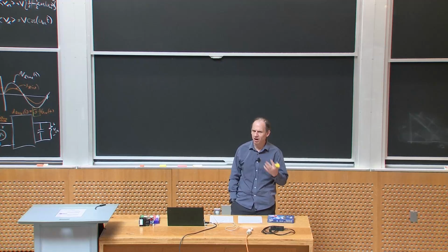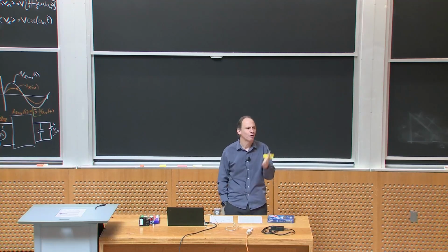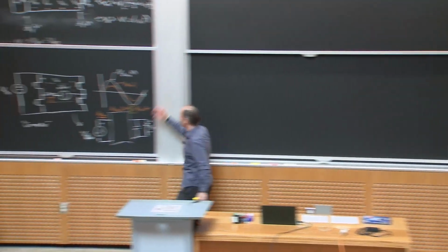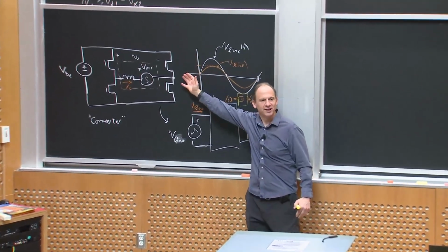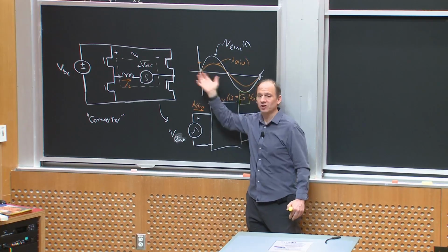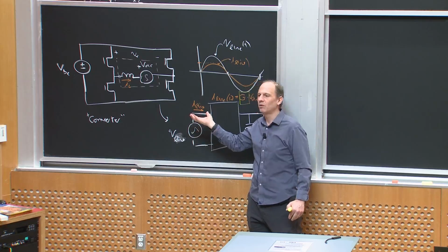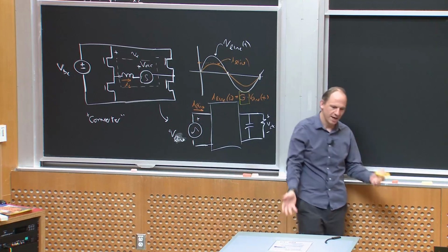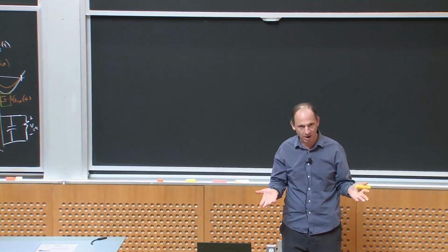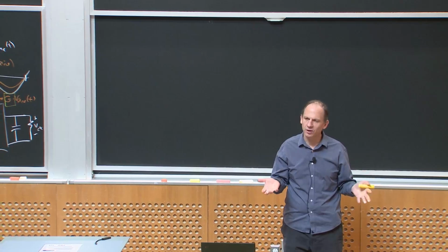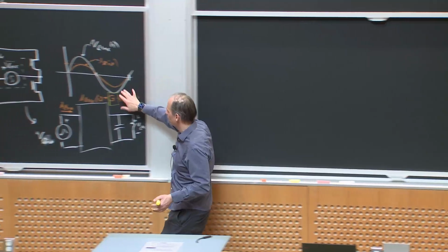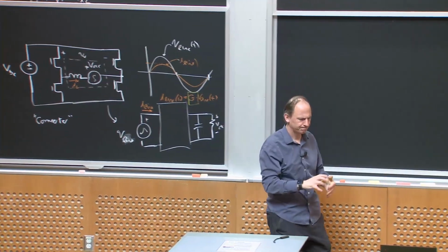More generally, in modern terms, people talk about a PFC, or power factor corrected rectifier. And what's meant by that is, I've shown you the idealized case where this draws a perfect sinusoid. You may have converters that don't draw perfect sinusoids, but are close enough that the power factor is very, very high. And so that would be called a PFC converter. If you look at many applications like computer power supplies or different kinds of tools, they all have slightly different requirements, but generally the power factor has to be pretty high. They limit the distortion in the current, or they limit how non-sinusoidal the line current looks, okay?